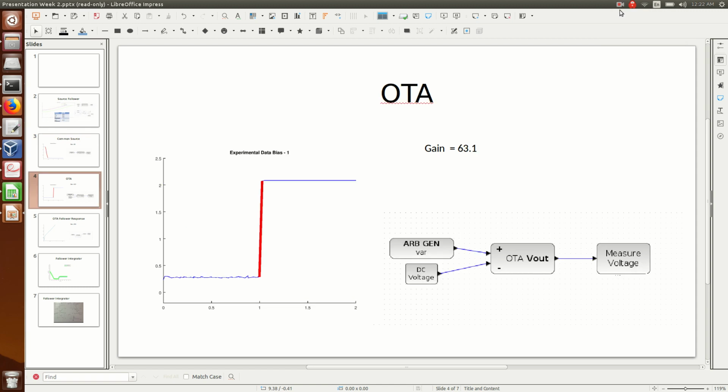Okay, so with the OTA, we have two transistors, both of which have a current through them, which is controlled by an input voltage at their gates. Both these currents have the same form that we've seen before, with the exponential, with the three different voltages which have to balance each other. So in this configuration, Vs is fixed for both of those transistors, so that's why their gains are controlled by the gate voltages.